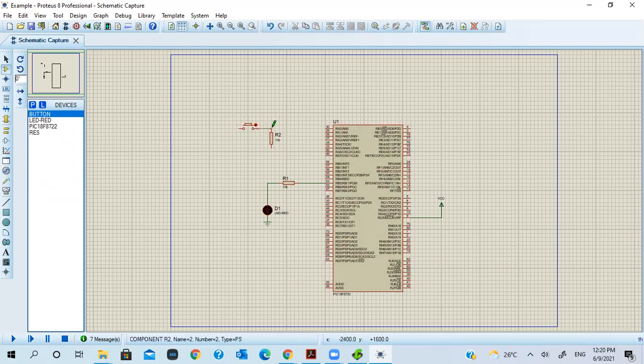So this has to be connected. Then this is connected. Since we are using an external button, it has to be using an external interrupt, isn't it? So let's connect it to port P because port P has external interrupts, right? Port P0 is external interrupt 0, port P1 is external interrupt 1, port P2 is external interrupt 2, and so forth, right? It's written over here, INT2, INT3, right? So that particular button has that particular characteristic associated with it.